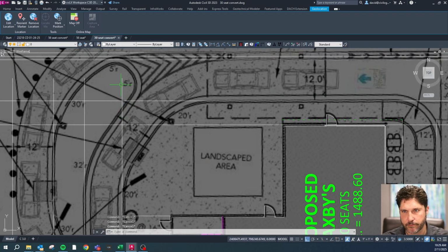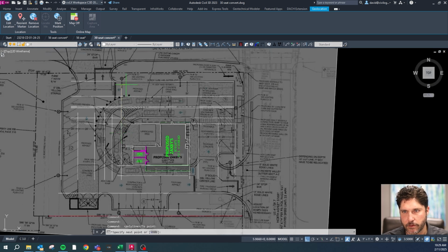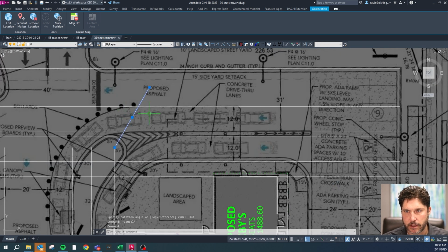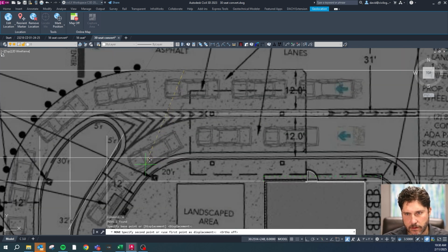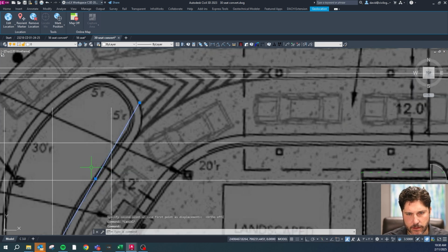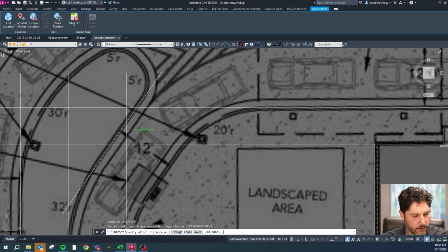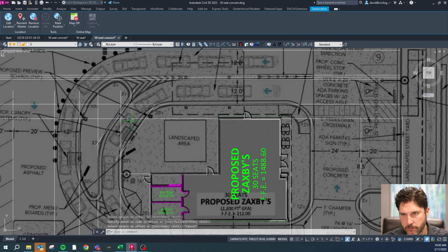I want to do an angle. I'm going to rotate this -30 degrees, and let's see if that doesn't quite line up. Let's rotate that another -5 degrees. Okay, that's looking pretty good. And move that over there, offset by 12.